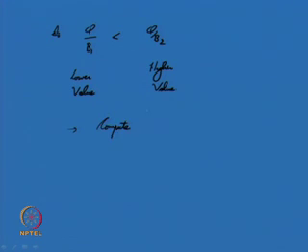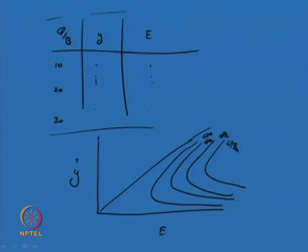In this particular channel section, compute q by b 1 and q by b 2 first, then go back to the curve. You have to interpret from this curve: for q by b 1, this was the initial depth of flow available. This is the depth of flow at cross section 1 1.